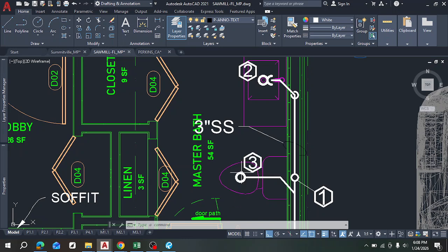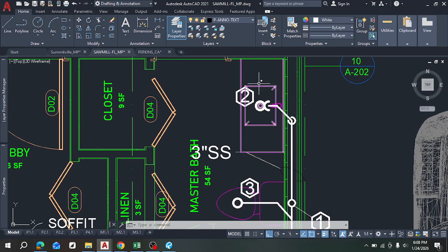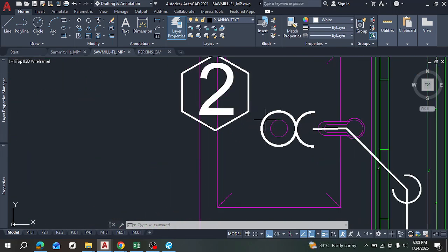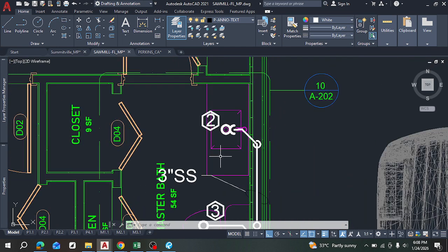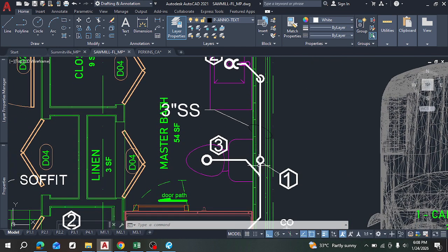So in this case, you see that I didn't add that. And also, this usually goes with smaller pipes. I mean, hence why solid waste shouldn't be allowed to pass, right? So then this is our vent. This just indicates a vent pipe that is vertical going up, right? And then this is the vent stack, where the pipe penetrates the roof and goes out to